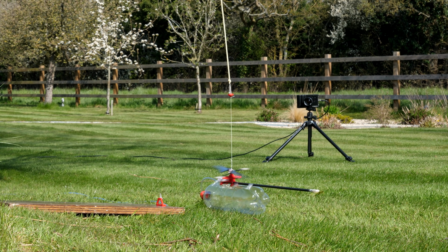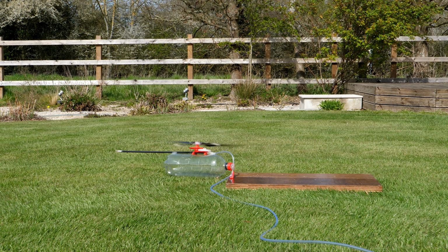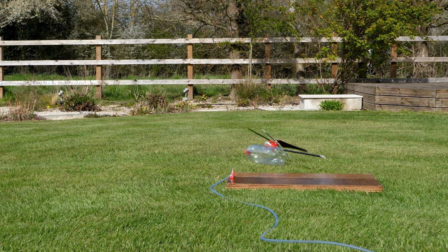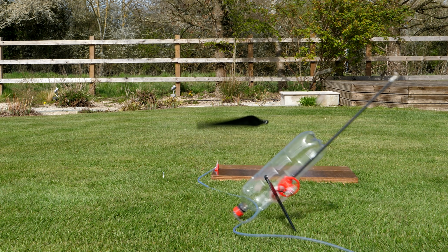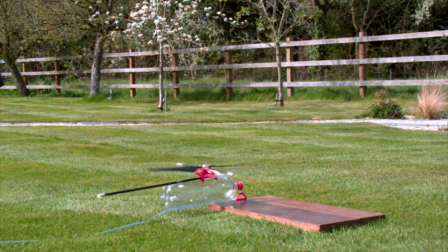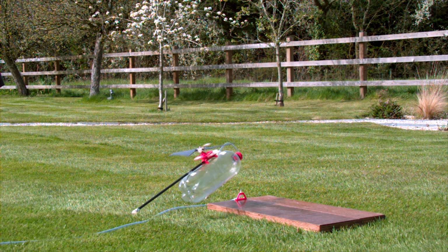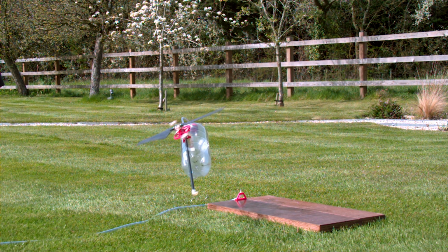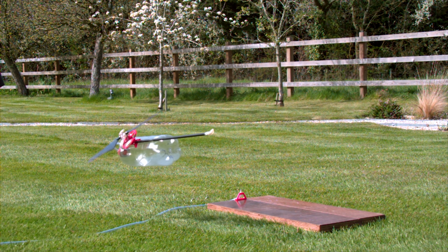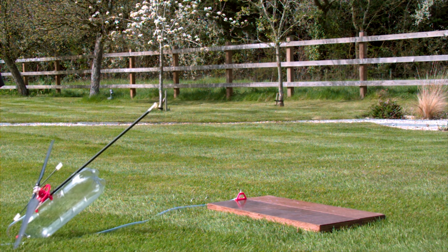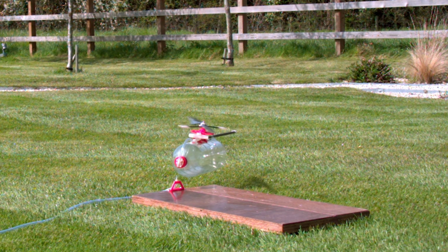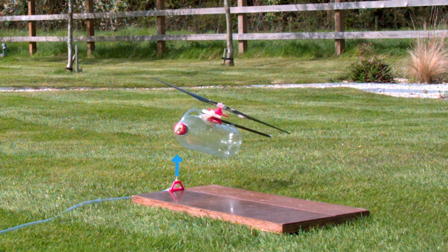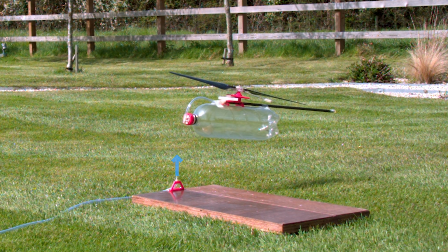And without the safety tether? It seems the nose of the helicopter pitches up very violently as soon as it takes off, which throws the stabiliser bar way out because it's only restricted to about 30 degrees of tilt. I think the reason for this is the air supply acts as a nozzle once the helicopter lifts off, producing a fast jet of upwards moving air, which hits the helicopter nose.